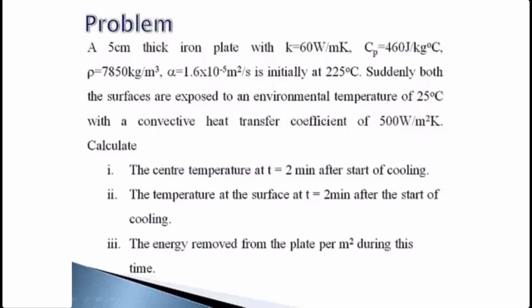Now after 2 minutes, what is the center temperature? Center means mid-plane, that center plane temperature, and also the surface temperature at the end of 2 minutes. So the question itself makes it clear there is a difference in center temperature and surface temperature. So there is non-uniformity in temperature, and you cannot apply lumped heat analysis. You should go for Heisler's chart in solving this problem.